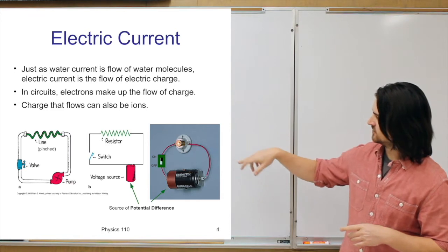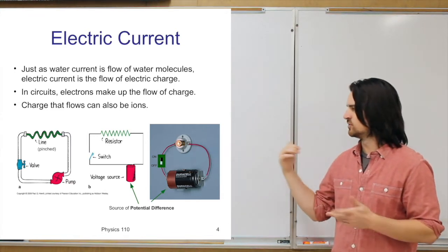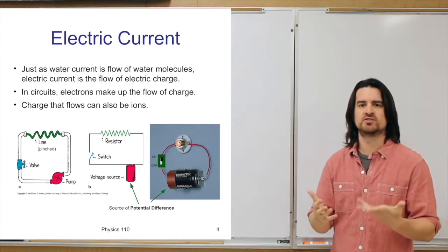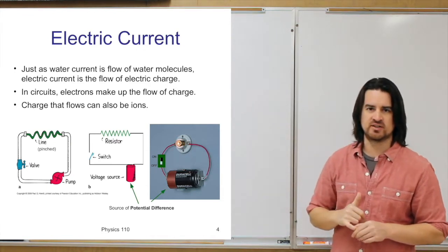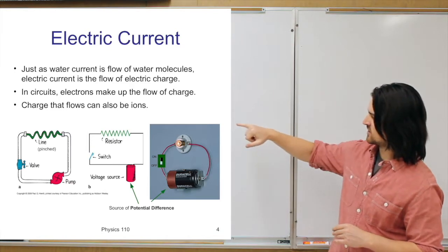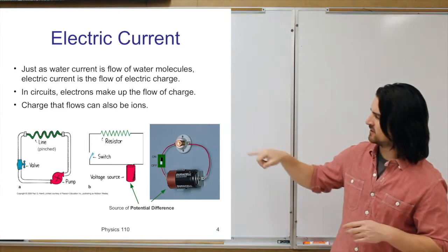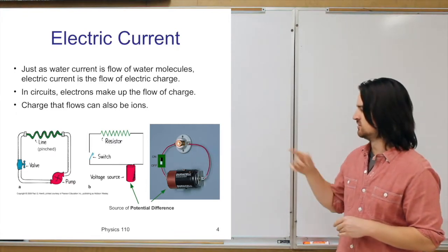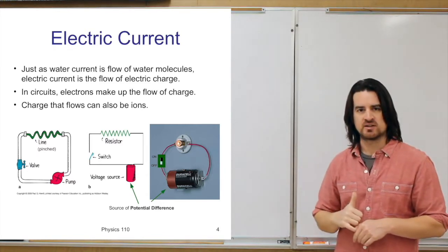And then those wires are connected to a light bulb, and generally, most light bulbs or all light bulbs act as some sort of resistance to current flowing. So that light bulb is taking the place of that resistor there. And then again, the other side of that light bulb is connected down to the negative side of the battery, and we have a complete loop. We have a place where current can continue to flow, and we've got a source, our voltage source, which sustains that flow of current.